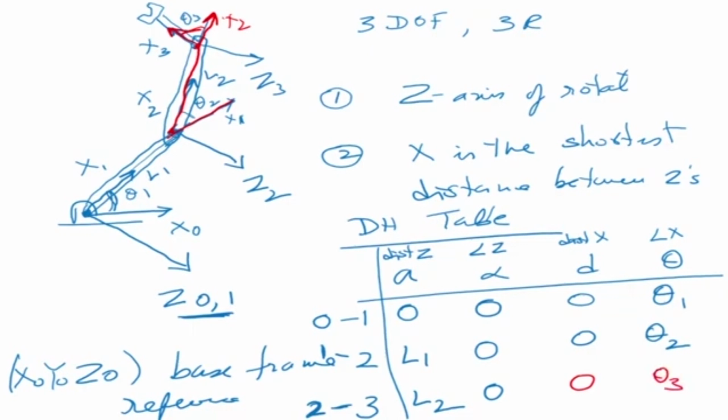So what we have seen is the DH parameter table, which gives us the values of the 4 parameters, a, alpha, d, and theta. Out of these, in a revolute joint system, when the robot moves, theta 1, theta 2, and theta 3 will vary. The others are all constant. This gives us the relationship between one frame and the previous frame. If you want to go from one frame to another, this table shows how many transformations are required.